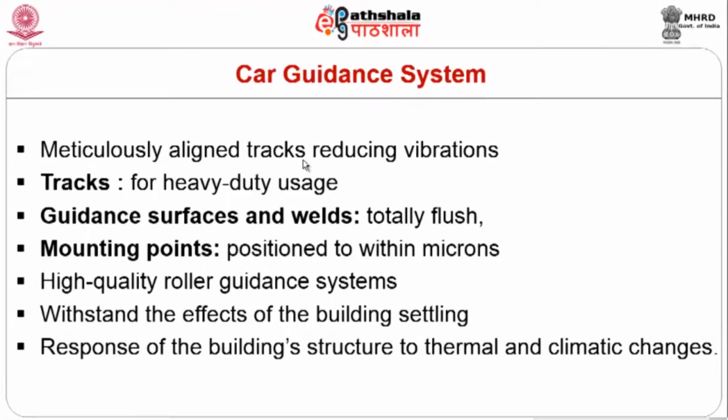And since the cars are going to move up and down for a length of time, durability of tracks is very, very vital, and therefore we make use of heavy duty usage tracks for the high rise elevator system. Guidance surfaces and welds have to be totally flushed so that they don't hit any components that are around the shaft.